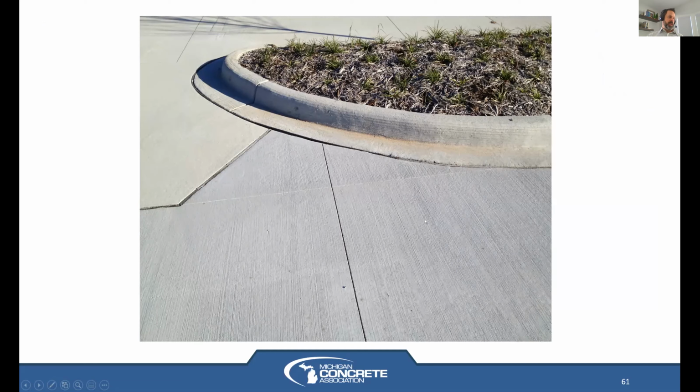What would we have done in this case? Well, this is what I would have recommended to be done. Take the two saw cuts, where they meet, stop them, combine them into one, and go perpendicular to the edge. So that cut and that cut would not be in there. We'd stop them, combine them into one. We do have this little slab here yet. So there's another, and I would have possibly not even done these two cuts where they had occurred, possibly moved this cut over slightly and handled it even different than what we picture here. But a minor change right there would have hopefully solved any problems, as well as some major changes would have been nice too.